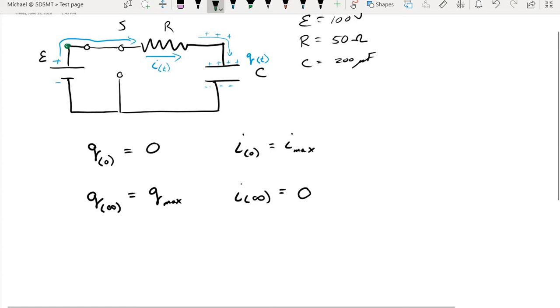I will just start right here at this random point, VA. I will choose to travel around the circuit in a clockwise direction. In other words, I'll go with the current. We'll start with our summation. Whoops, that's not equals. We start at VA. We pass through the resistor going with our current.